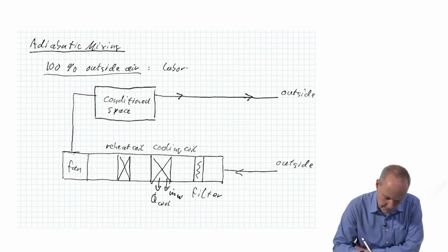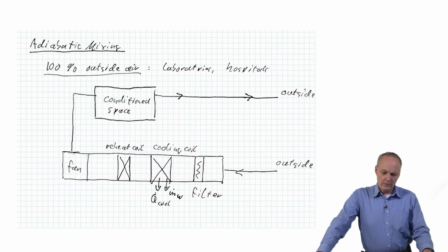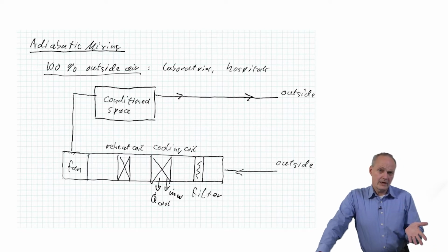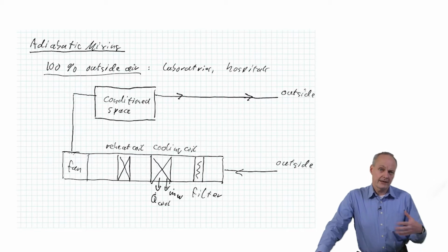for laboratories, hospitals, and so on. So there's clearly quite a bit of energy loss going on, and sometimes, or nowadays almost always, you try to remediate that situation by recovering some of the energy from the conditioned air that you're discharging.